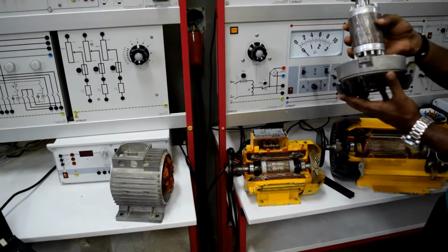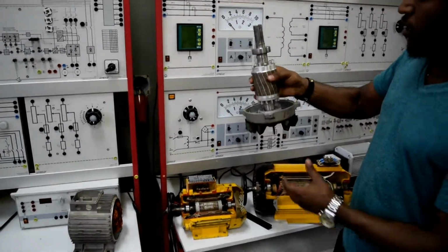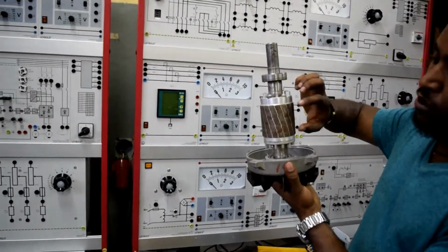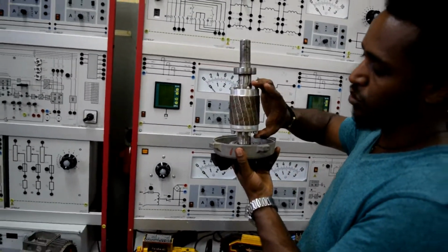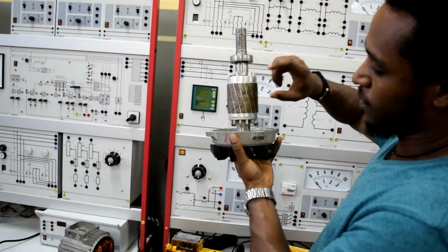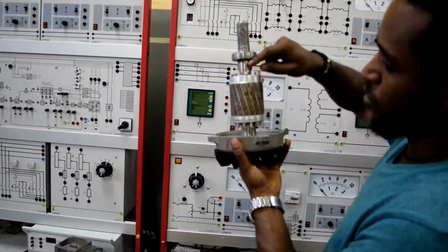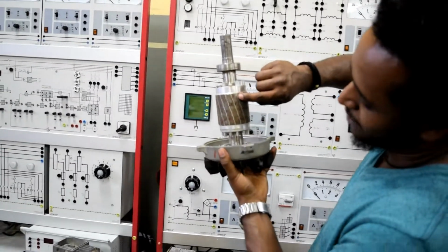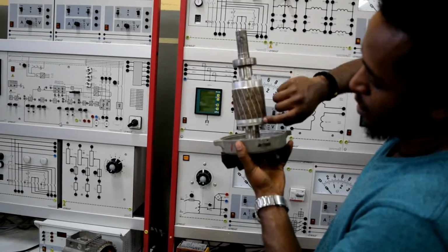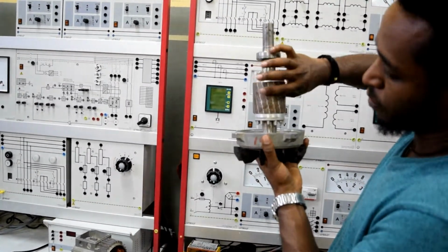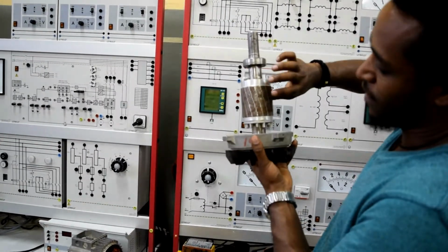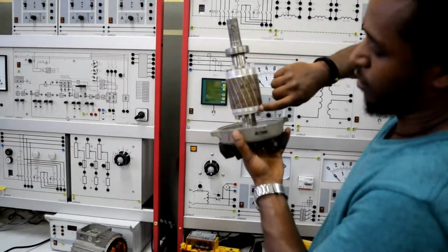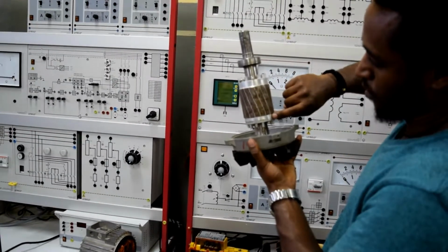So when we see independently, this one is the rotor. For the rotor of a squirrel cage one, we put the iron bar inside and short circuit it by using a short circuit device here, the aluminum rings. And we slightly skew the rotor slots. Why? In order to reduce the magnetic hump and the interlocking tendency inside the machine, we slightly skew the rotor for a squirrel cage one.